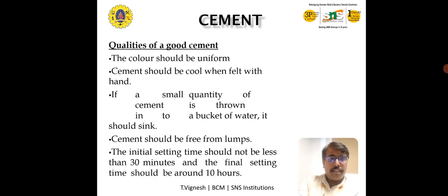Regarding qualities, the color should be uniform, and cement should feel cool when felt with the hand. If you take it in your hand, you should feel it cool. That is a good cement. If a small quantity of cement is thrown in a bucket of water, it should sink. It should not float like normal powder. Cement should also be free from lumps, because once lumps are formed, the quality is reduced.